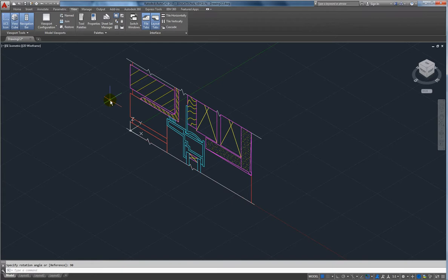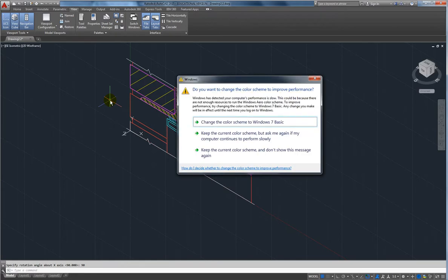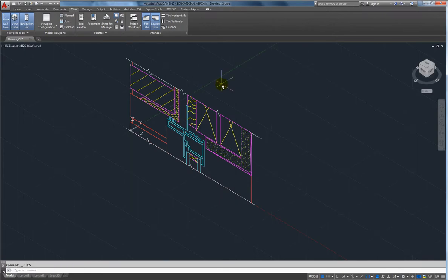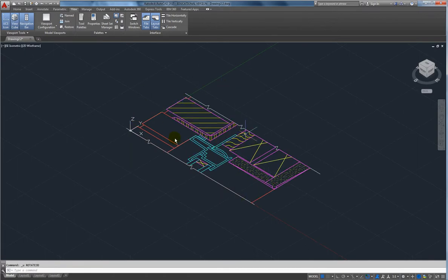Which one do you guys think is easier? Maybe this is easier. But we're going to need the UCS because now if I want to start drawing there, I still have to do the UCS X90 to get it. So this does both in one action. And you still have the drawing. I mean, we can copy rotate it. Okay, but it starts getting you thinking about the rotation of the UCS more than the rotation of the object.